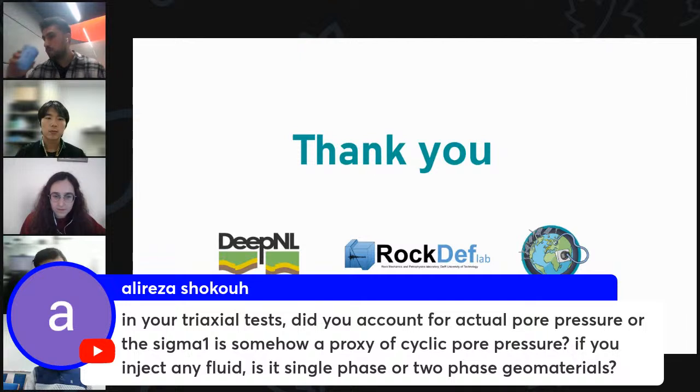So others asked, in your triaxial test, did you account for actual pore pressure, or is sigma 1 somehow a proxy for cyclic pore pressure? If you inject any fluid, is it a single phase or two-phase geomaterial? I assume he asked it for the first part of the setup.